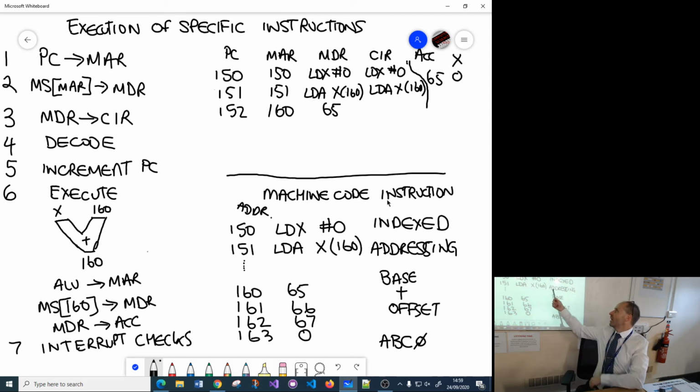You have a fixed base value that might be 5, and then an index register that points to the start of a record, and you increment that to the next record because you want to read the 6th item in a record. Okay? So index registers allow us to access arrays, which are the most efficient for, but you can also access records of data.